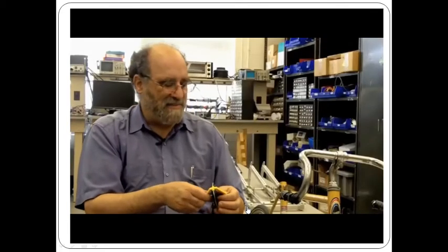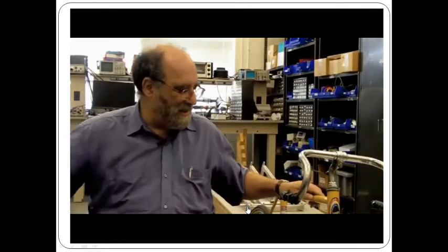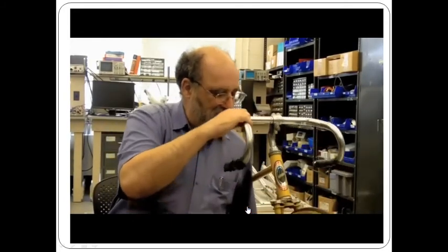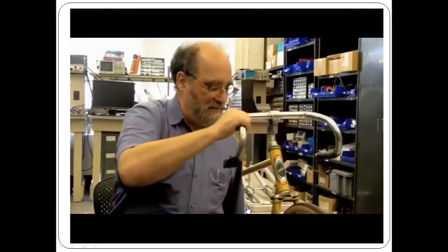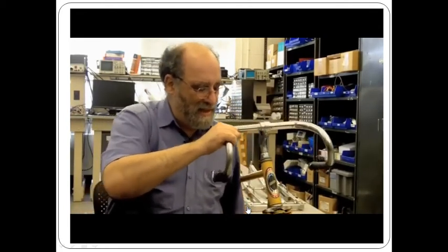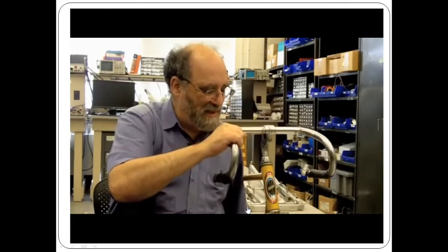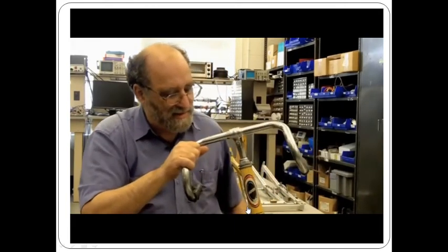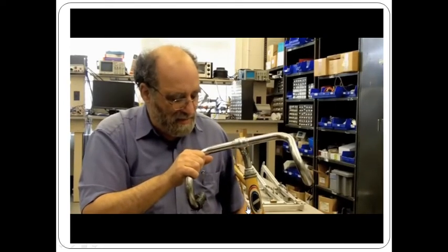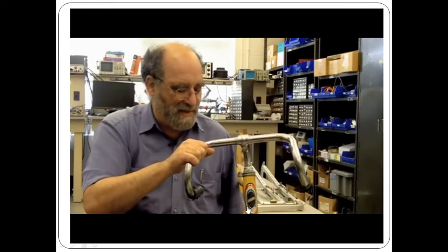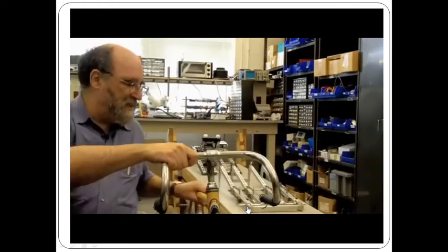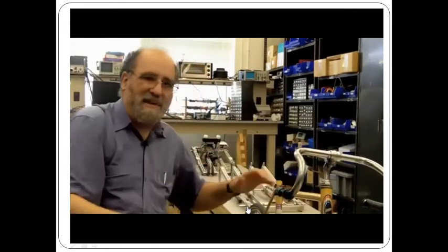And the net effect of that is that for a bicycle wheel, imagine this bicycle wheel is spinning like so. When the bicycle tips to one side, this wheel acts like a gyroscope, and the net effect of this tipping is that it causes a steering. And then the result of that steering is that the bottom moves to the side, and the wheels are brought back under the bicycle. So that's one of the explanations for how bicycles can be self-stable.